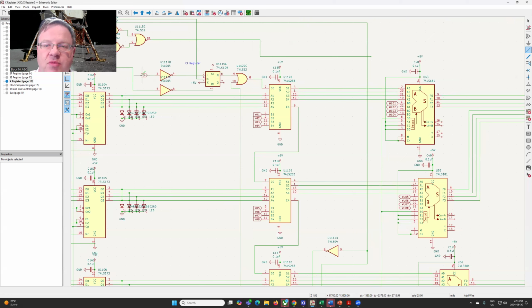So what we have here is the logic where the CI pulse comes in. We invert it because, of course, we have negative logic on control pulses. We store that carry in the flip-flop, and we can then combine it: either the carry comes in from our carry bit or it comes in from our end around carry, and that provides our carry in for bit 1.